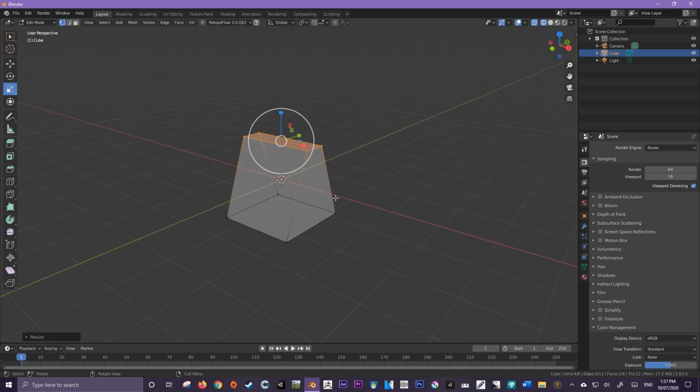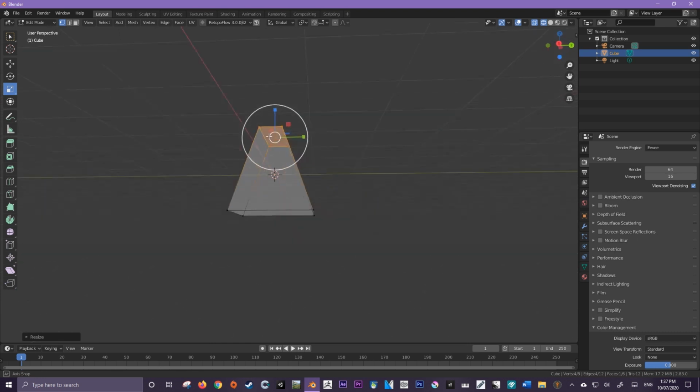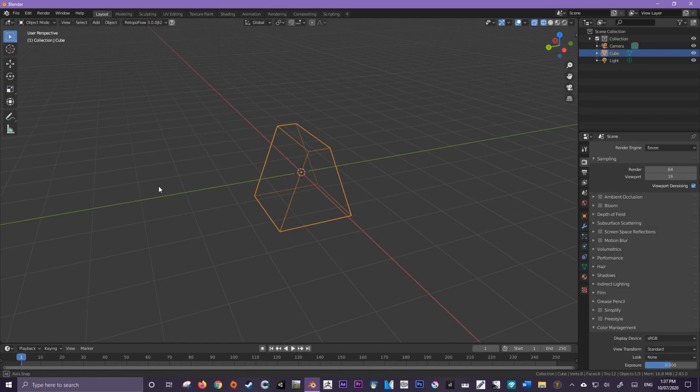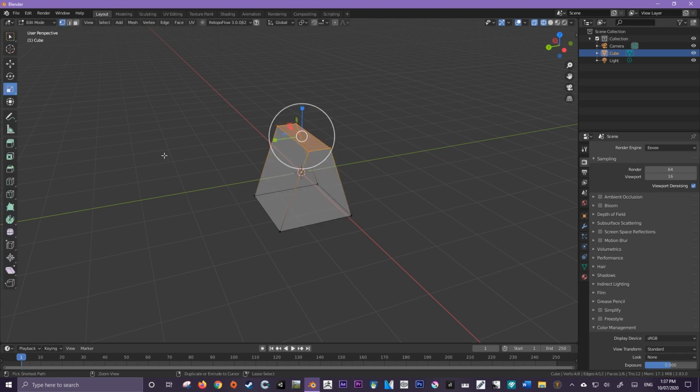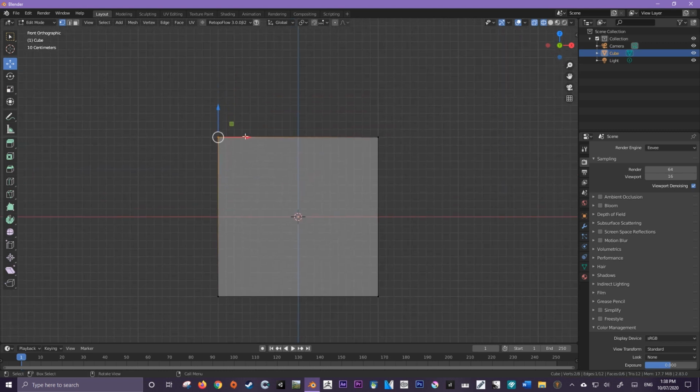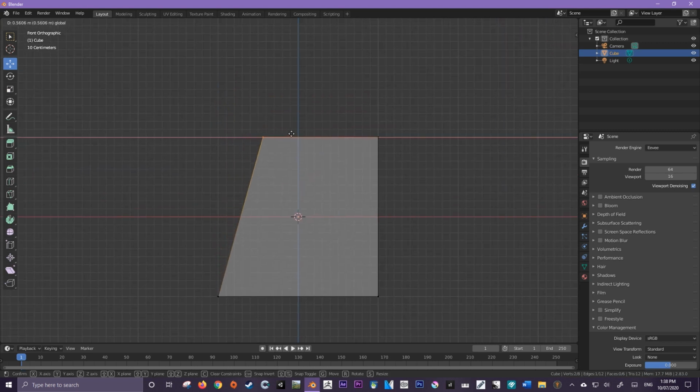So now we've created a little sort of triangular shape, even though the top's been cut off by the looks of it. So we can make this type of shape using the scale tool. Now let's do the same thing, but let's use our move tool instead. So instead of selecting both of these sides, what I would do is double tap A to deselect everything, I would just grab one side, grab my move, and now I'm going to move it. But we want it to be equal on both sides, so I'm also going to press Control to snap it to the grid.